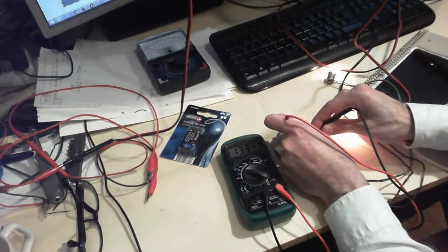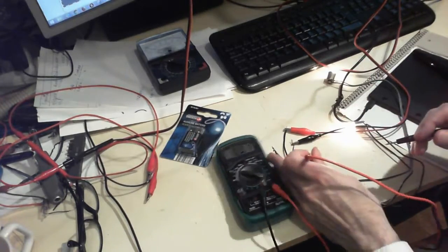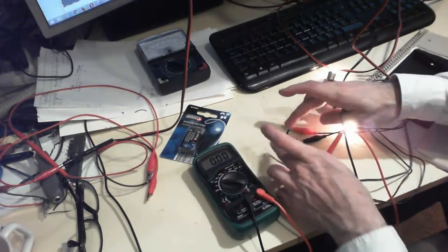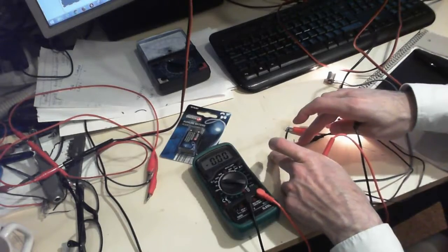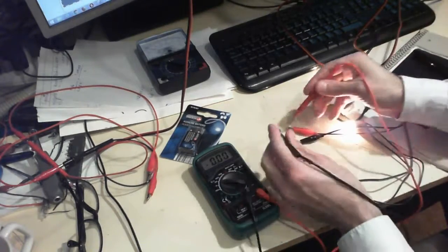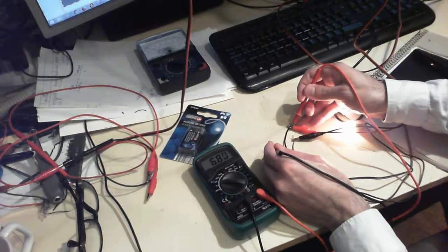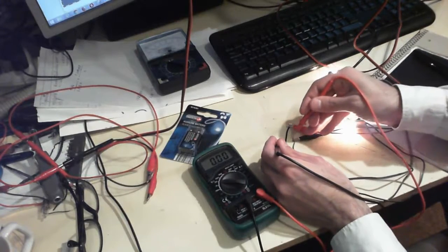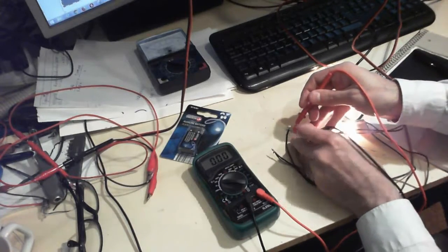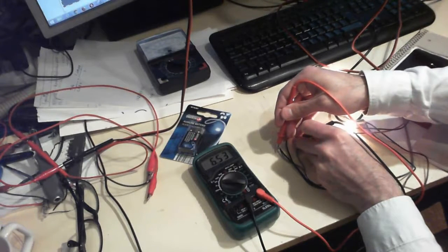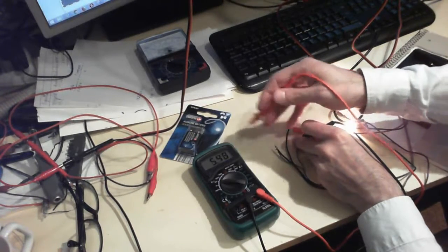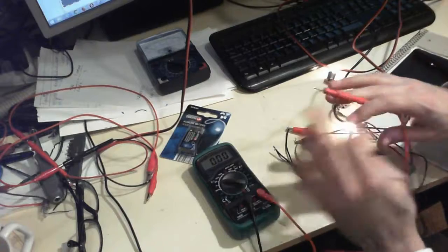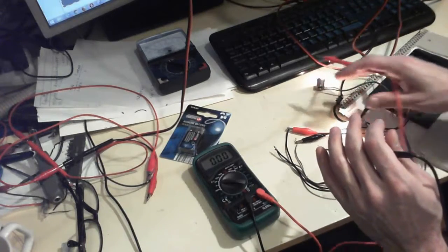And you're reading 13.3 volts, right? And then now I'll probe one of the lamps. This is one of the lamps, and then these two will be the other lamp. So one of the lamps here is 6.8 volts. The other lamp is around, I don't know, let me see. This is positive here. So this is 6.5 volts. Which if you add them up, you'll get around 13.3, which is the power supply here being shared by the two lamps.